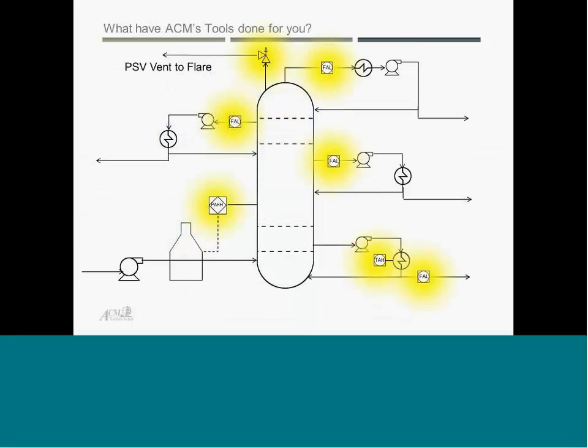Finally, and possibly most importantly, at the end of the Hazop, we had 7 safeguards overall from the 20 consequences. The bow tie helped us remove 5 of those and replace them with 1. So we've gone from 7 safeguards to a total of 3.